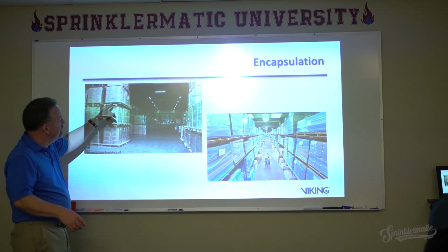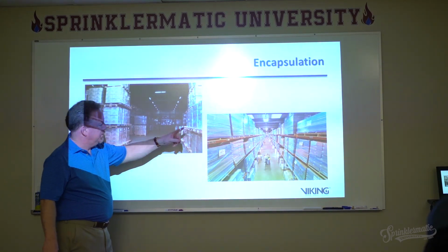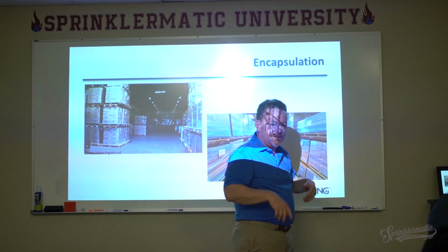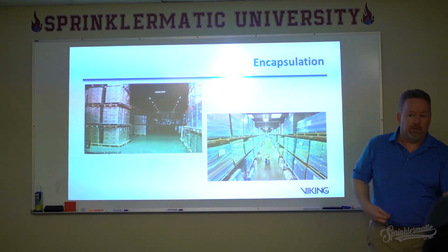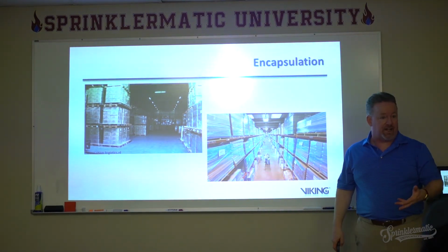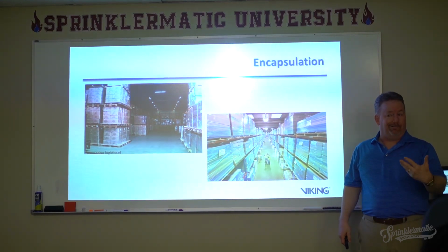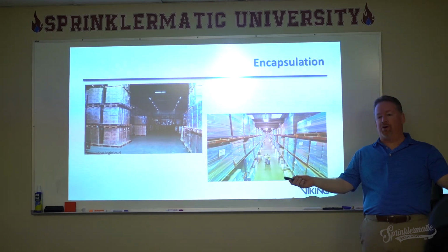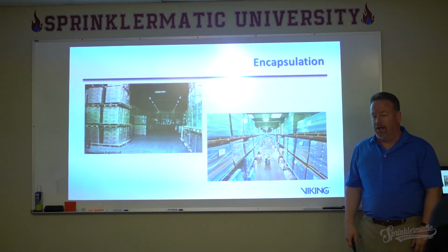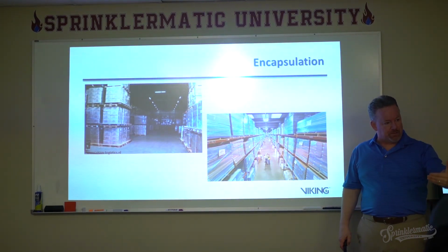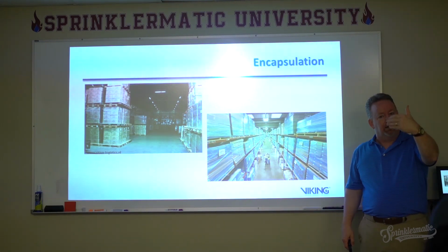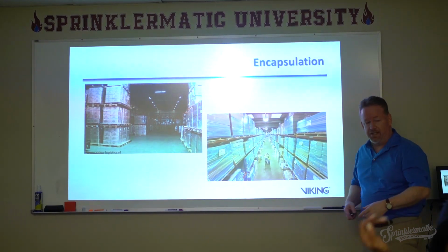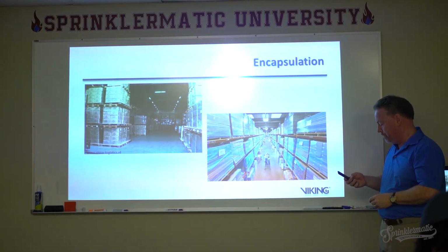Not so much individually wrapped, but when the pallet load is wrapped, you can get a decent burn going in there before it breaks out. You can't get the water inside. So what do we do? We say you can't store it that way, or we increase the amount of water that's coming out. You have specific adjustments that you make when we have encapsulated storage.